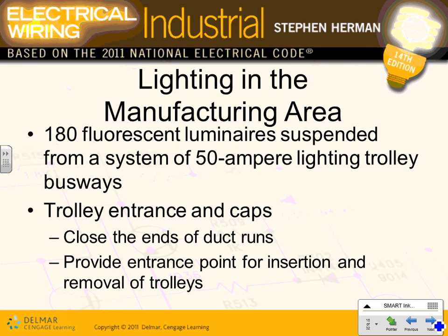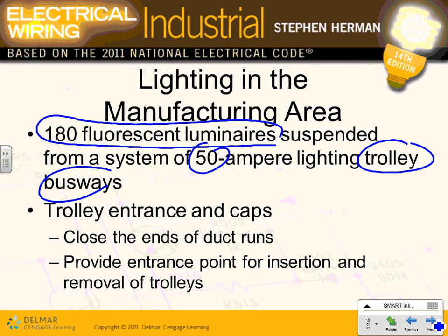That's kind of unique, guys. They have 180 fluorescent luminaires suspended from a 50 amp trolley busway, so they can move them along the manufacturing floor. That's their decision. Trolley entrance and cabs close the end of the duct runs and provide an entrance point for the insertion and removal of the trolleys.